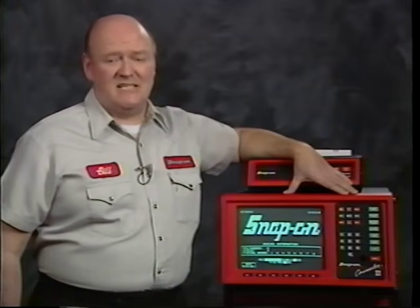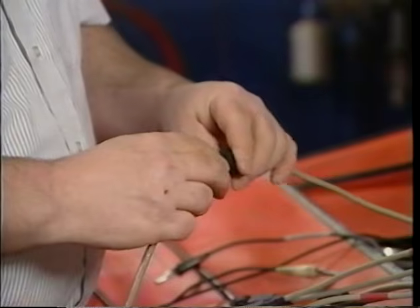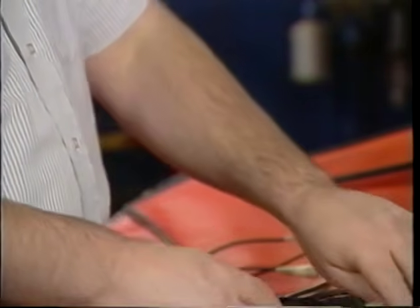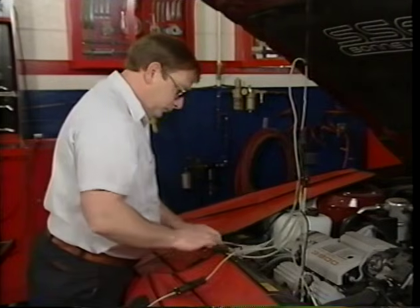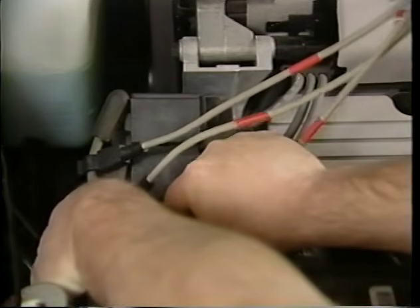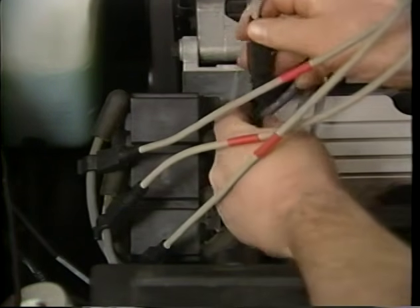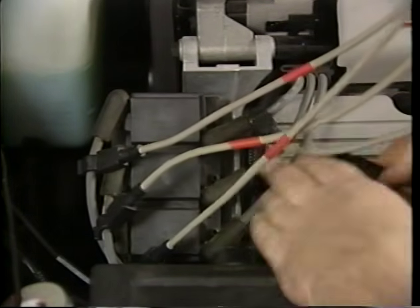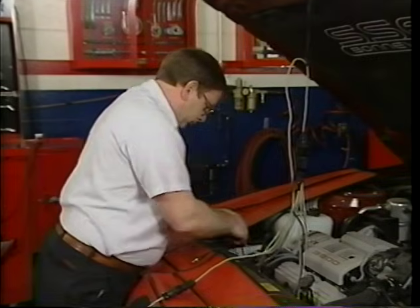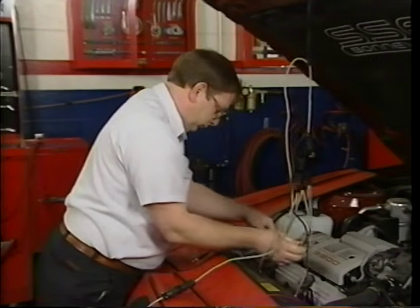Connecting the lead set is easy. All you have to do is plug the secondary lead into the DI terminal block and connect the dual capacitive pickups to the spark plug wires. Keep the clips of red-coated leads together and away from the clips of white-coated leads. If the test pattern jumps around on the screen, turn the engine off and move the two groups of clips further apart. The DI lead set is available as an optional item.